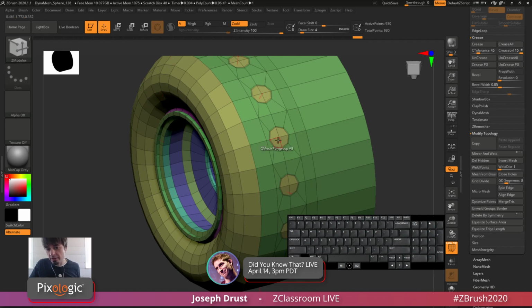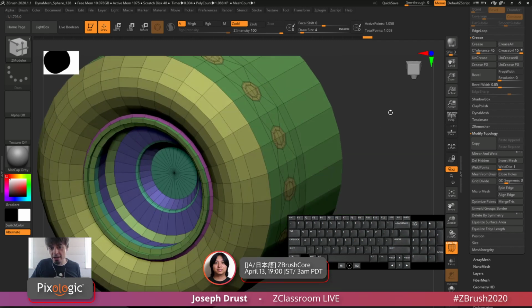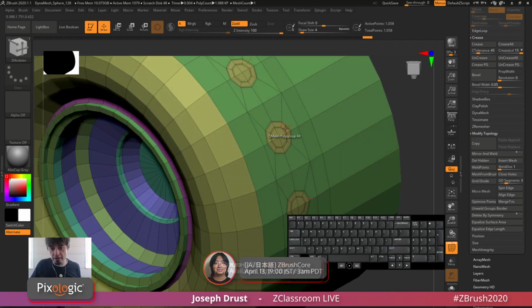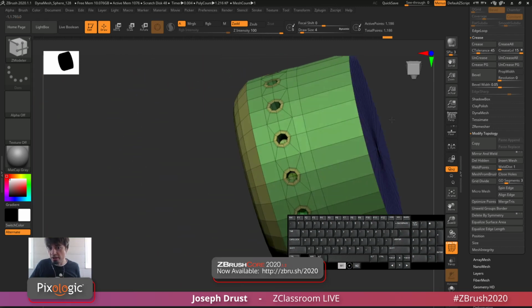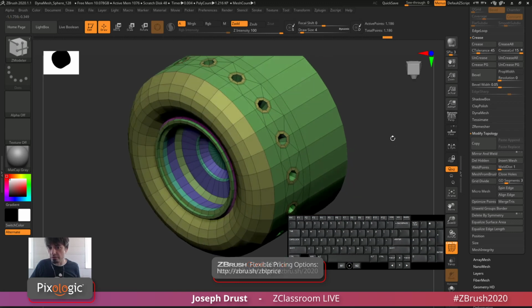The next thing with this kind of stuff, I usually double it. So I'll do one point and then I'll do another one. It's just adding another layer of protection to the circle: splitting once and then splitting again. Now I have this ring, which is another layer of protection that I can then smooth out and keep that transition flowing nicely, rather than having it go from here to here. Then after I have these, I'd grab those, and you can Q-mesh them in. That's how I'd handle circles on the edge.